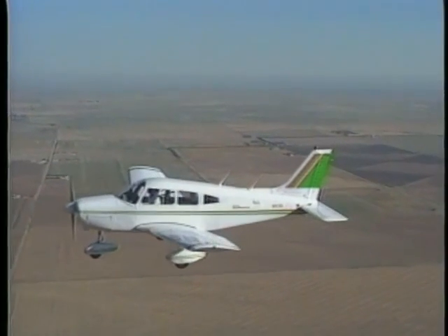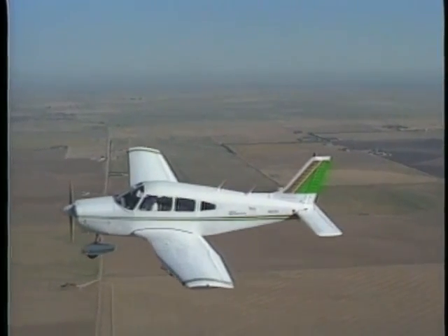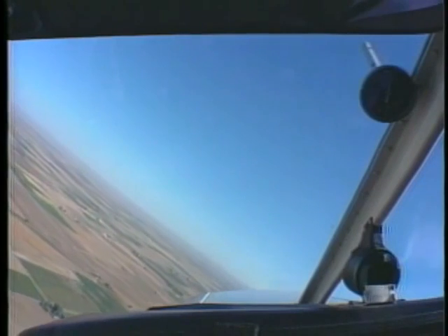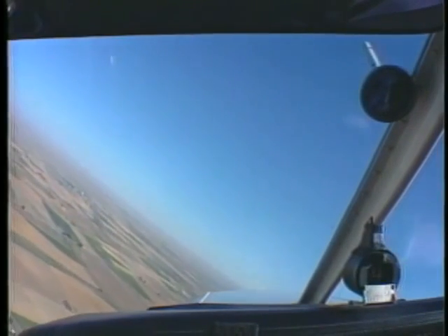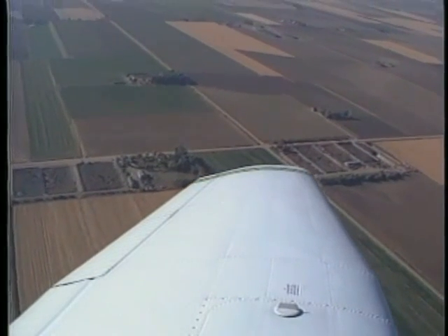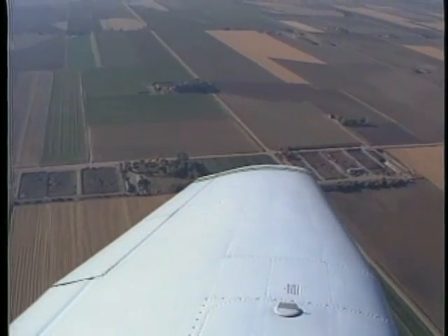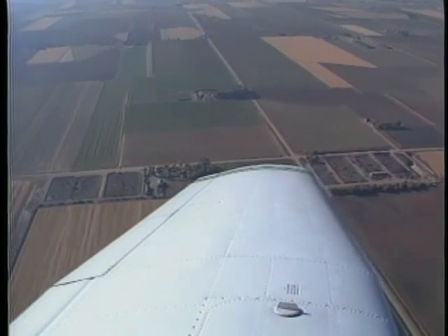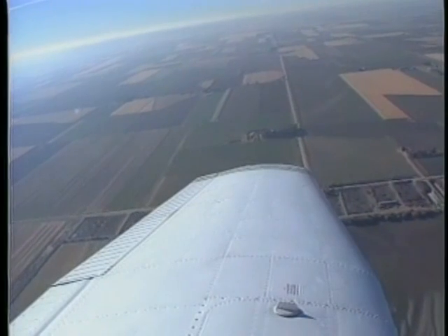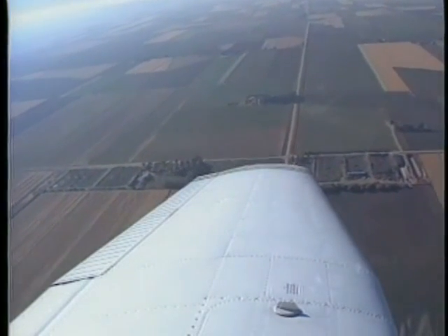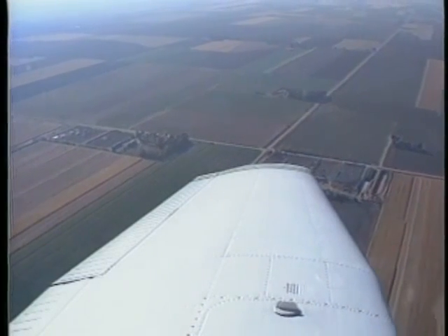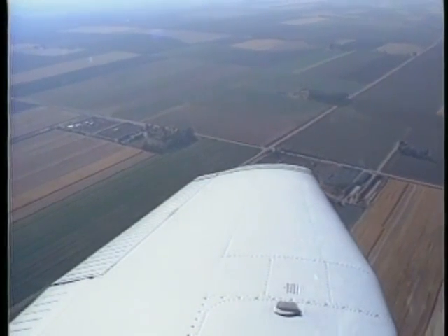When you're approximately abeam the first pylon, roll into the turn. At this point, your ground speed is highest, which means you're at the highest pivotal altitude. As you continue the turn into the wind, your ground speed gradually decreases. If you fail to adjust for the reduced ground speed, the reference point moves behind the pylon. This means you're too high. To bring the reference point back to the pylon, lower the nose to descend to the pivotal altitude.